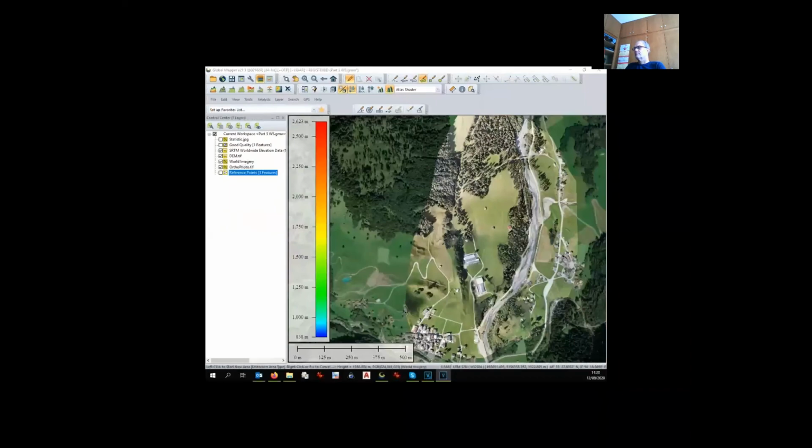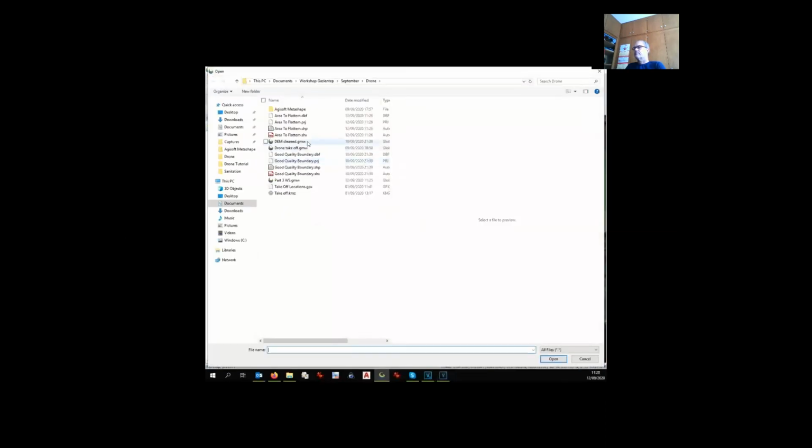I have prepared in advance all the areas that I would like to be flattened. It means I have identified all the trees and the sheltered houses that I don't want in my digital terrain model. I look for this shape file, which I called area to be flattened.